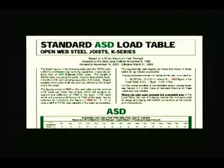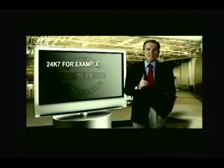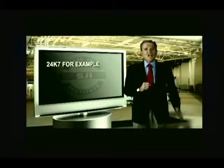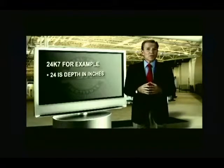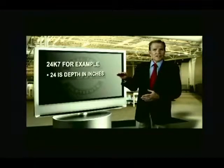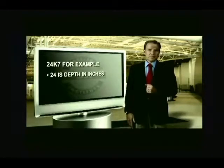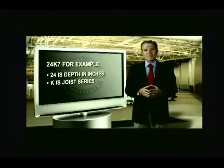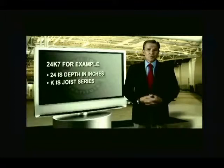The wording above the load tables is very important because it explains the significance of the values in the load table. The load tables list each standard joist designation. The first number is the nominal depth, so 24 means 24 inches from the top of the top cord to the bottom of the bottom cord. The letter or letters denote the joist series: K for K series, LH for long span, and so forth.